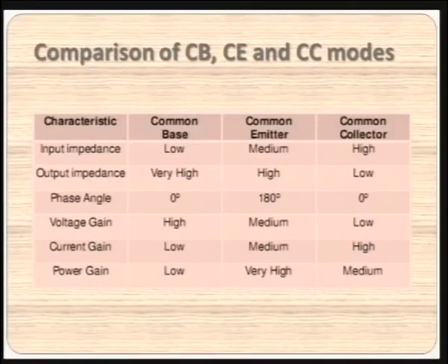Now let's have the trend of the values for these three modes of operation. Let's have a look at the table again. In the common base mode, the input impedance is low and the output impedance is high.